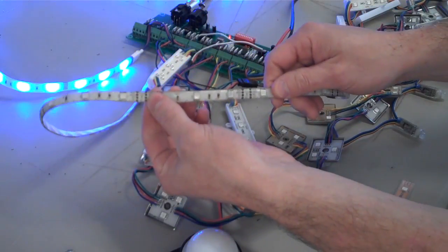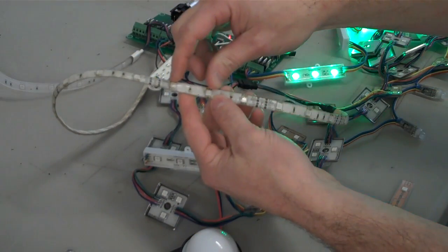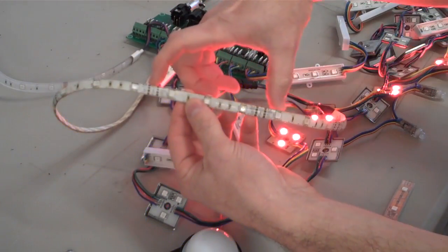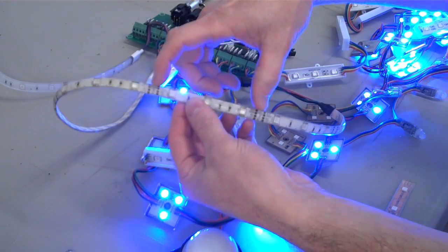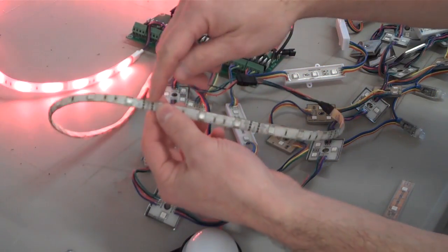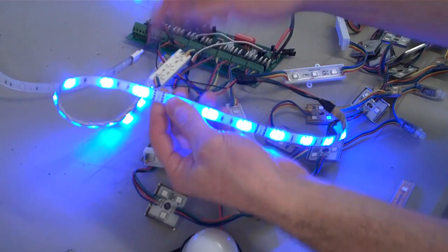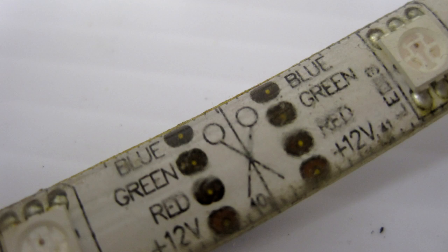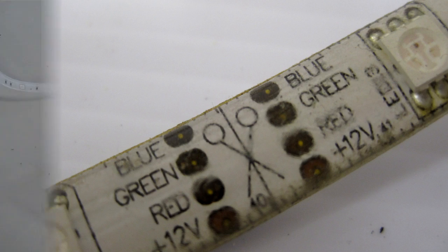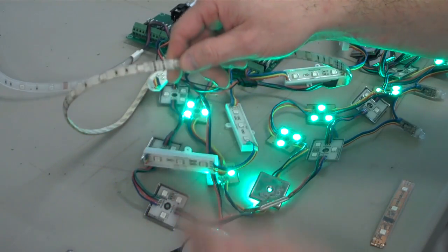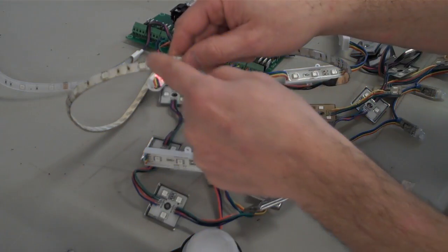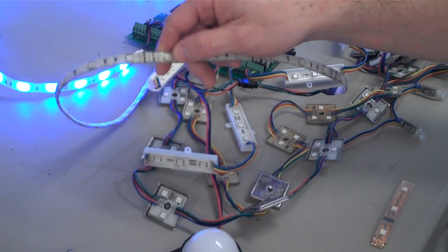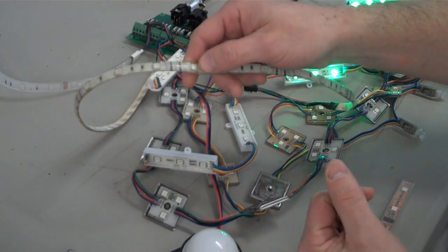They vary in distance. For example, you can see that these are, in this particular case, 3 per section, and each section is about 100 millimeters, or about 3.5 inches. Within strip, most often you can cut it, and there's an indicator here for cutting it here or here. These little black spots are where you're able to resolder wires. So if you needed to go around a corner and make a 90-degree corner, you could cut that, splice in a small section of wire, and then continue off in a different direction.